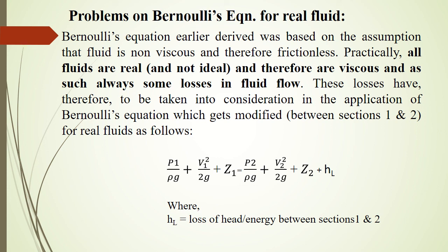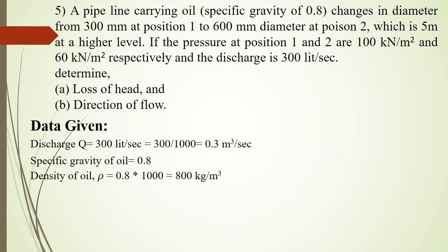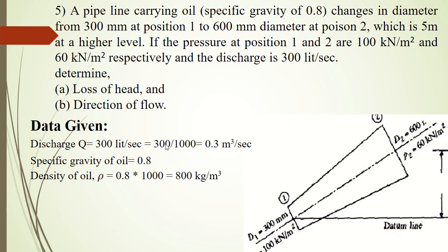To put it in a very simple way, when you come across a real fluid, there will be some losses due to viscosity. Those losses you have to add in the Bernoulli's equation as shown in this formula. So here I just applied that concept to this problem. The data I'll just write down here.